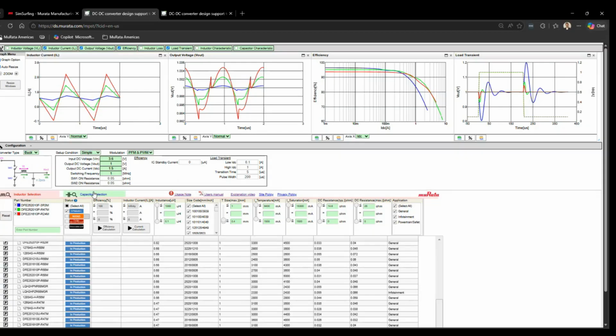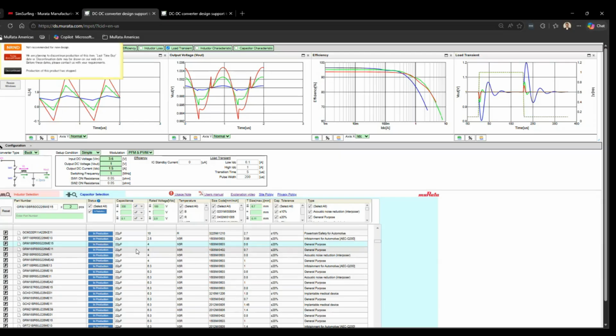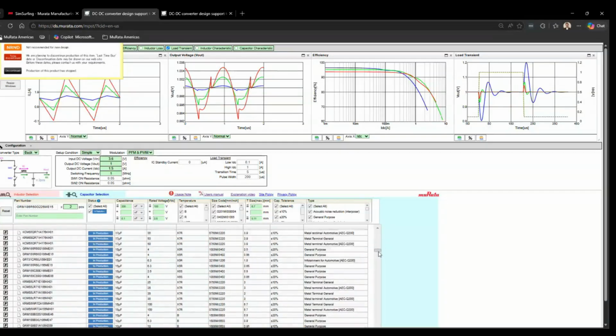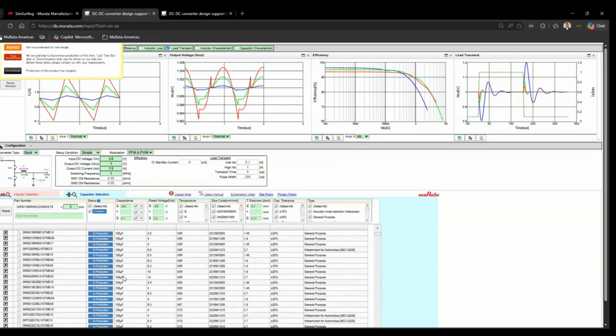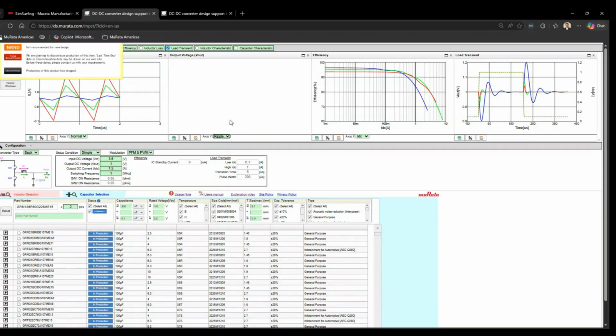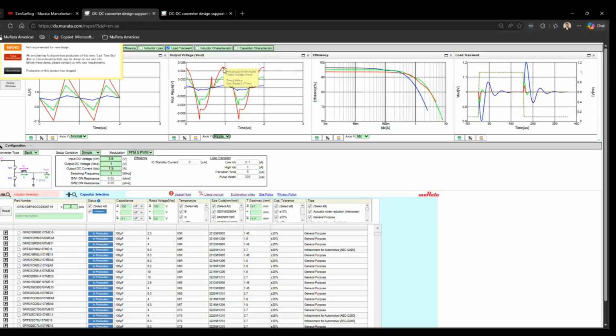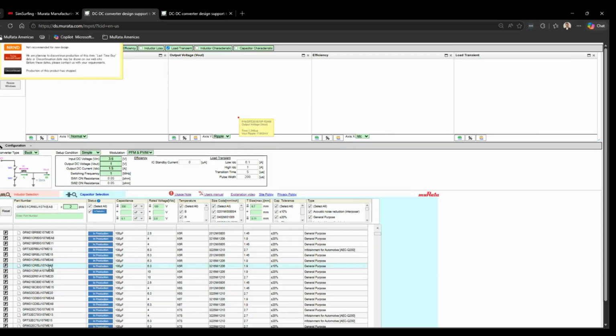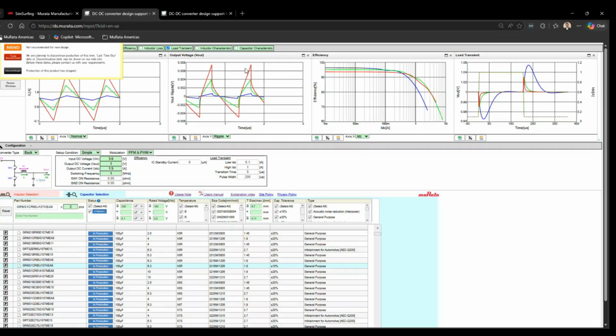And then for output voltage, if we go to the cap section, so here it automatically used a 22 mic part. Say we want to use higher capacitance to smooth that voltage a bit more. So let's go up, rather. We have some higher bulk capacitance here. So you can see, let's go and check for ripple. And you're getting about 4.7 millivolts of ripple. And let's change this to maybe 200 mic parts. And you can see here the ripple went down a bit.